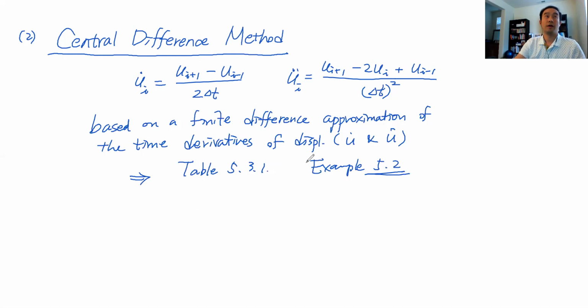So you might remember that we have a half sine wave function for the p of t. We apply this excitation into the single degree of freedom system, and we should be able to find out all the values at a certain time step, and the responses with the actually four different methods, because we have two kinds of variations under the Newmark method.